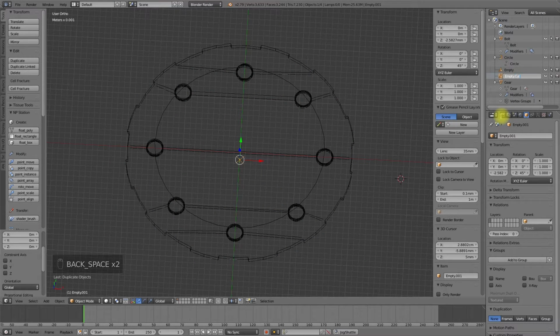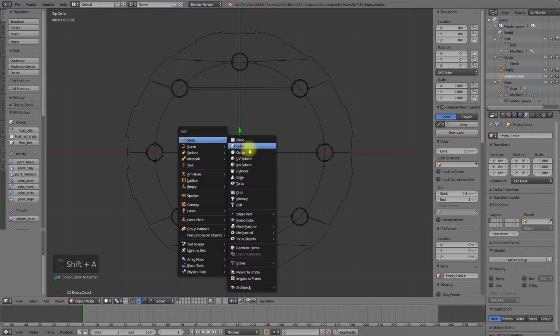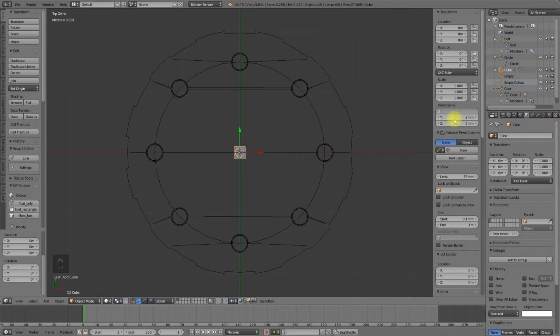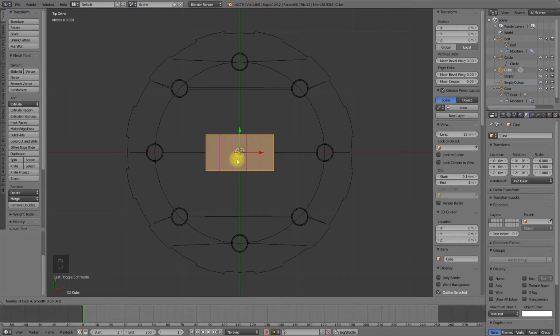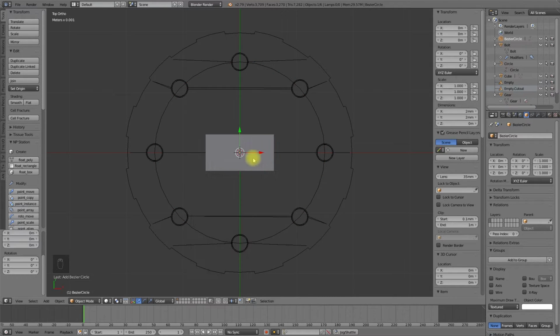In the example of the video, I used the curve modifier in combination with the cube object to create circular arc sections. In order for the modifiers to work, as for example the curve modifier, care must be taken to ensure that the objects have enough subdivisions or geometry the Blender functions can work with. A simple approach here is to slice the starting object appropriately.